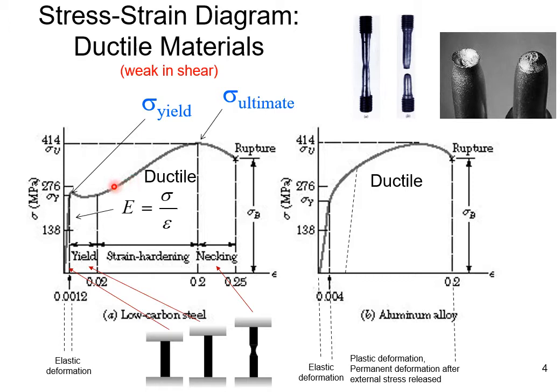In the plastic region, there are a few things that can happen. The material can yield, where the cross-section remains the same, but the material exhibits plastic deformation. It can go into strain hardening, where the dislocated grains become entangled as they move past each other, giving additional friction.